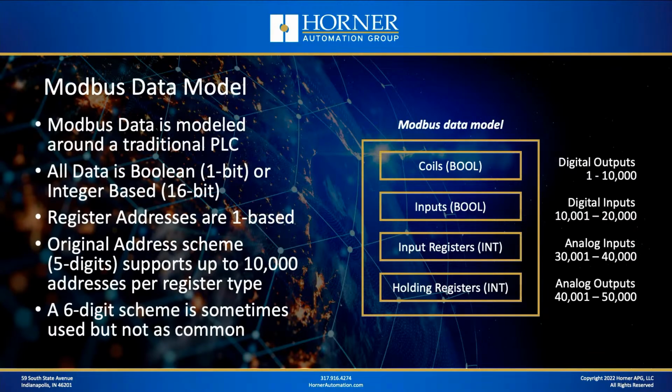And you can see on the far right there, those are the traditional 5-digit Modbus addresses for each of those 4 data types. Now, there's also a 6-digit scheme because as PLCs have gotten larger, they have more addresses than just 10,000 per section. So there's a 6-digit scheme that's sometimes used, but frankly, the 5-digit scheme is still more common.